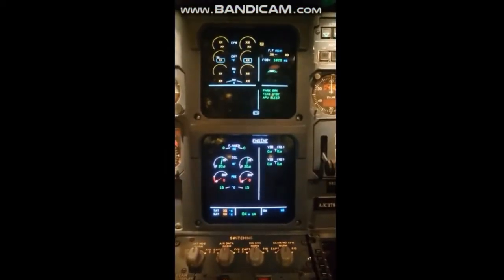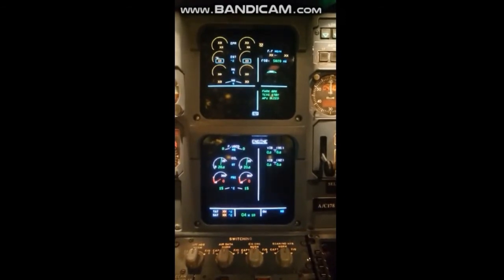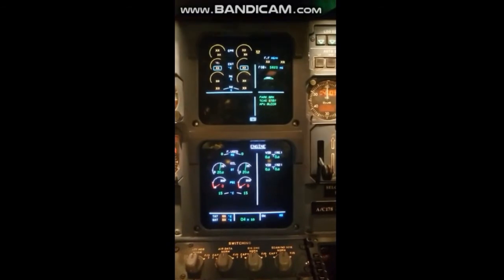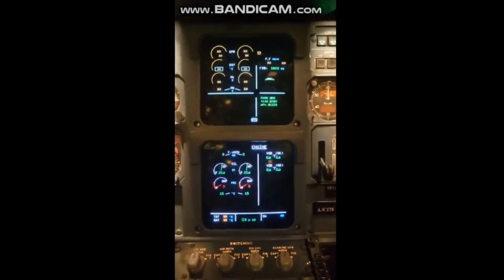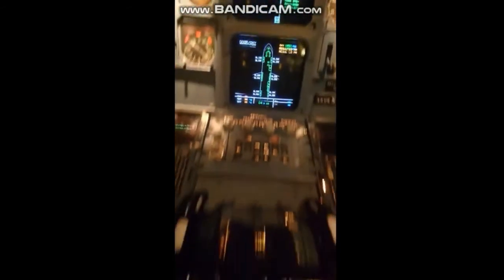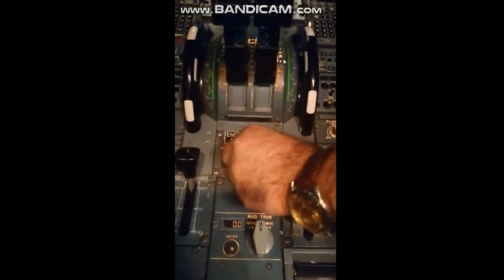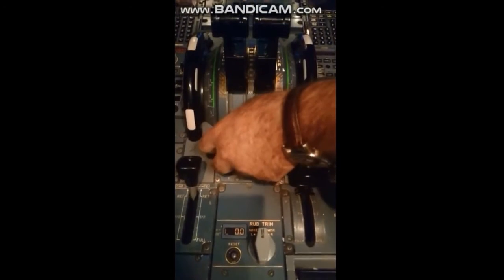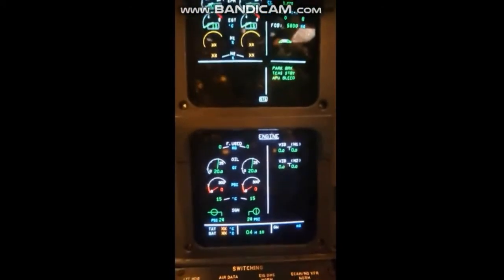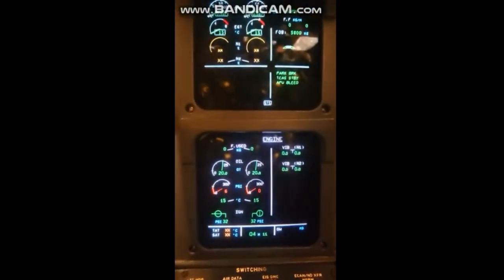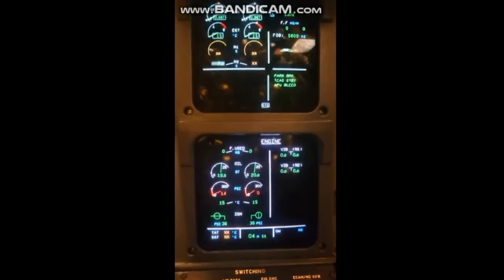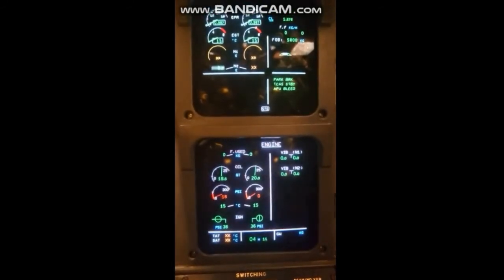We are in an Airbus 320 simulator. We will do a hang start simulation during automatic engine start for the V2500 engine. We will start engine 1 automatically. Now ignition start, master lever on, so the start valve is in line. N2 will start to increase now. Oil pressure increases.